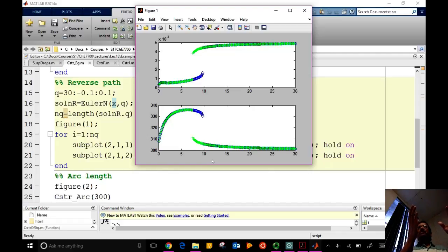The same ideas are applicable in Taylor-Couette flow, in hydrodynamic stability problems. When you have multiple states, how do you get from one state to the other? Only through external perturbations that are large enough to take it away from one stable steady state to another stable steady state. I think we worked on something like that in one of our previous classes.